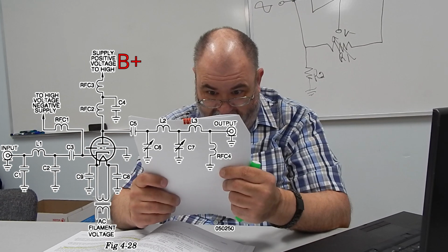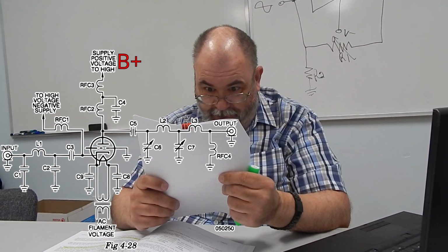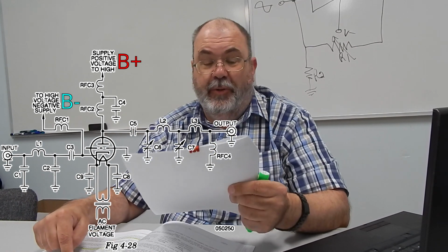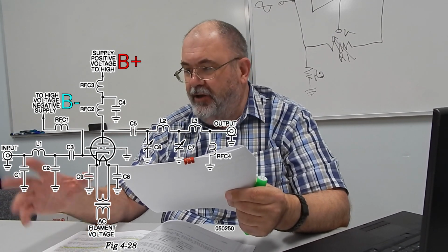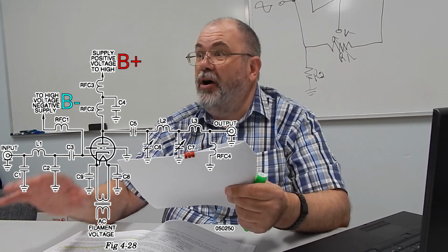The grounded grid cathode choke connects to B minus, or bias is another word for that, by the way. But on the exam, the answer is B minus. So the Industry Canada guys, or ISED, whatever they call themselves, use B plus and B minus for those terms, which are the old terms. The guys who worked on tube equipment know all about B pluses and B minuses and all that kind of stuff.